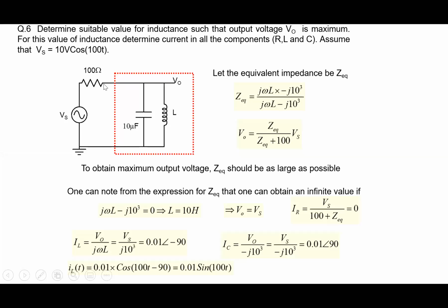So again, this notion of current division that we have, that a current comes in and it divides between two currents, and the currents into which it divides are necessarily less than this original current, all of that fails here. When you have negative values of impedances and positive values of impedances, things can cancel each other and result in 0 current, but current here and current here.